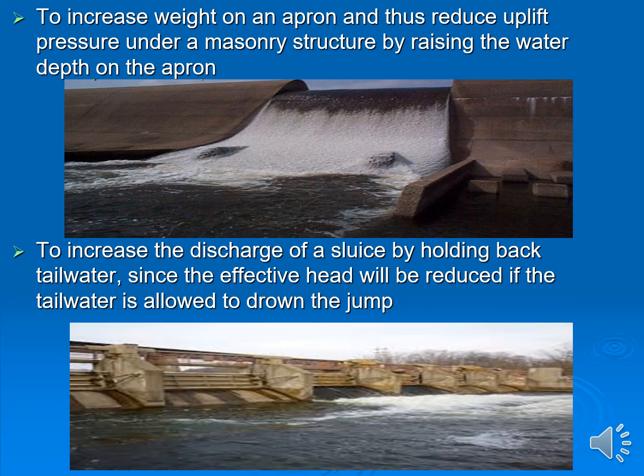To increase the weight on an apron and to reduce uplift pressure under a masonry structure by raising the water depth on the apron, and also to increase the discharge of the sluice by holding back tailwater, since the effective head will be reduced if the tailwater is allowed to drown the jump.